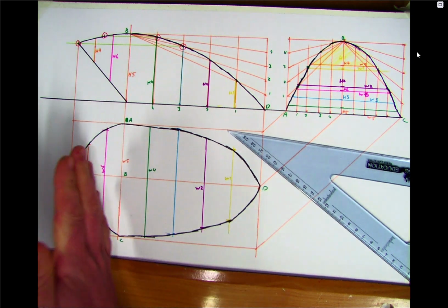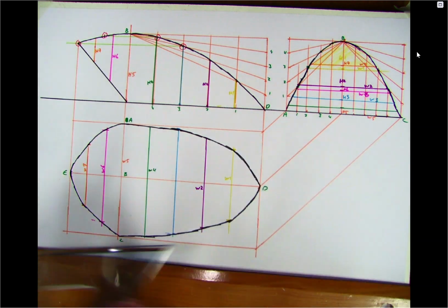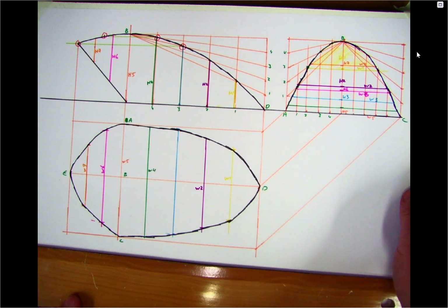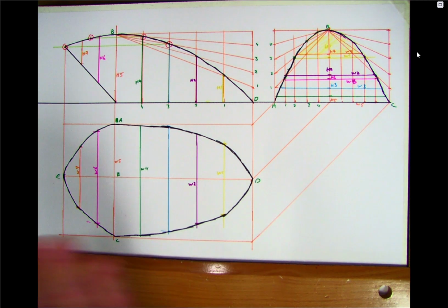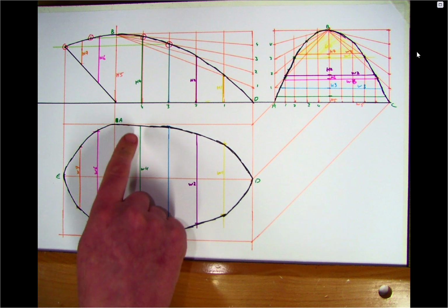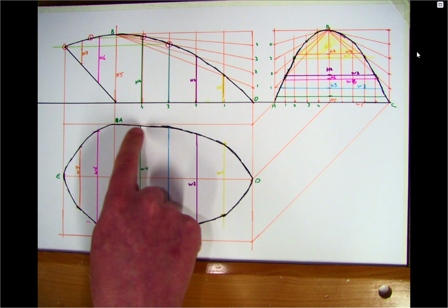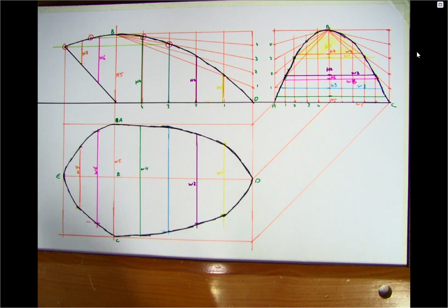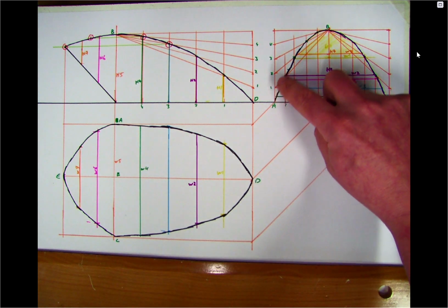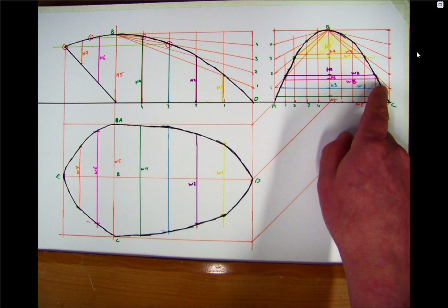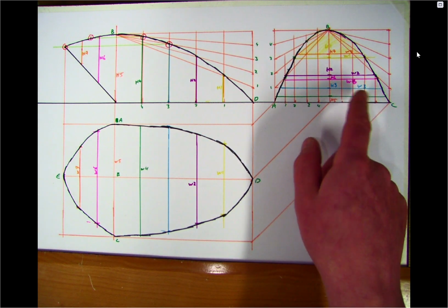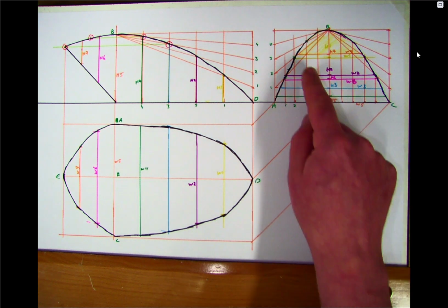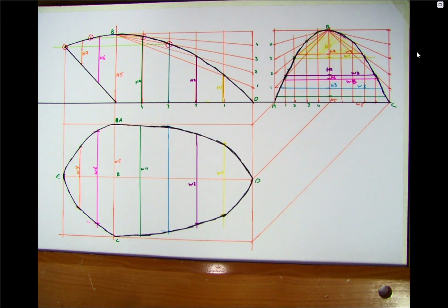I found the left hand side by using the shorter distances, the right hand side by doing this. I've used some nice neat colour, which makes it a little bit easier to read. And if I'm an examiner looking at that, it's very, very quick. As I said, there's a small inaccuracy in my drawing. This should look a little bit further in from this side, so it just looks a little bit jaggedy there. Then what I would do at the end is come back maybe with my Tipex pen or my rubber, and put a little hidden detail line here. But we needed it to be solid initially, because we don't know where these heights are going to hit and find our widths. So that's the question.